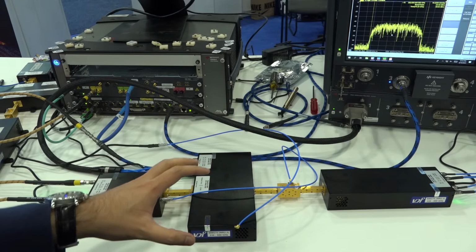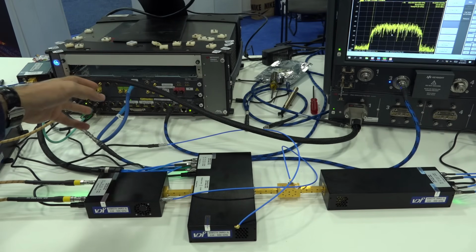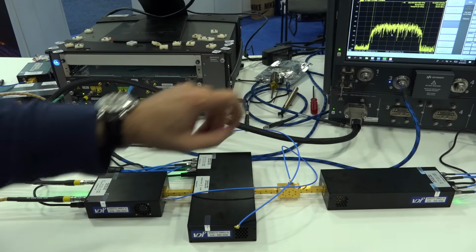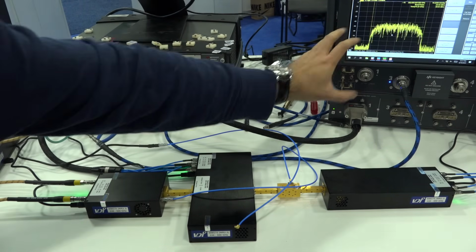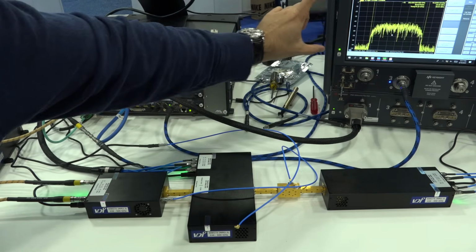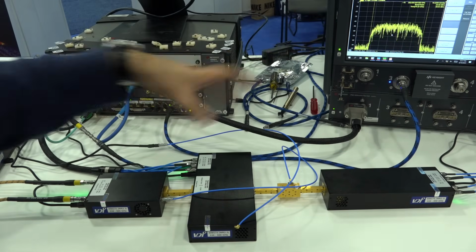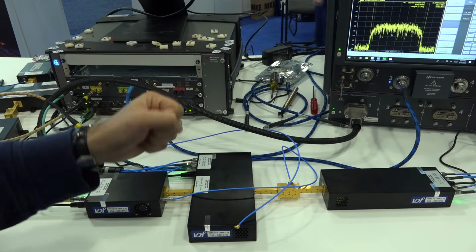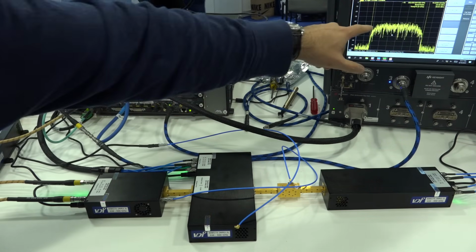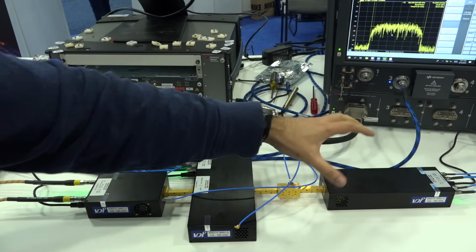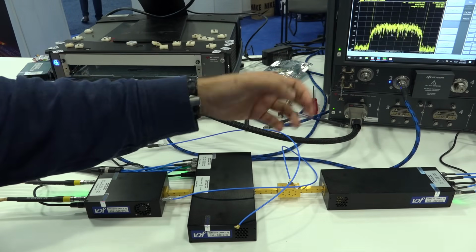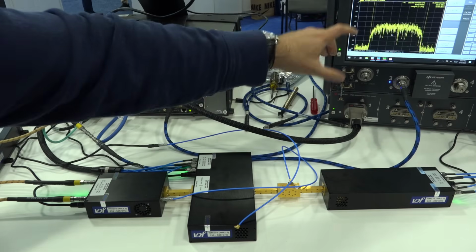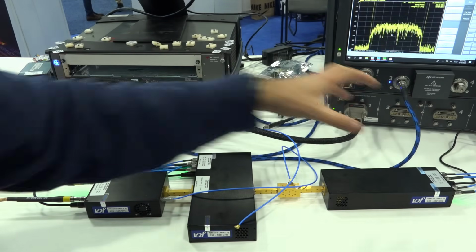Now this is using a technique that combines an arbitrary waveform generator from Keysight with a frequency stitching EVM assessment that PNA-X can do. This itself is a completely different measurement system where you have to do basically stitching the frequency characteristics by using an S-parameter measurement as a reference, and then from that you extract the EVM characteristics of that modulation. Now this is pretty useful because if you have a very, very high bandwidth, let's say you're doing an occupied bandwidth of 20, 30 gigahertz around this frequency, you don't want to have a digitizer. You can do this directly using the PNA-X and the VDI modules at the same time.